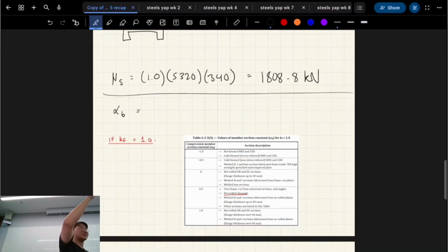I've got a little demonstration thing here. So here's a piece of wood, basically. I'm just going to pretend it's a truss member in compression, or a column or something like that in compression. So in tension, if I pull on this, the length of the actual thing has no contribution to how strong it is. That's why you get cable bridges which span 100 meters or whatever. Cables are purely in tension. The length of them does not reduce their strength.